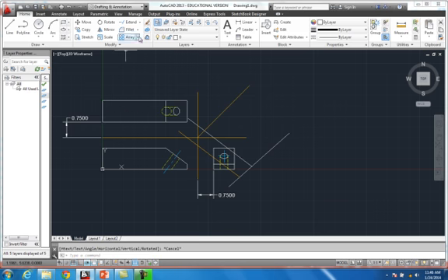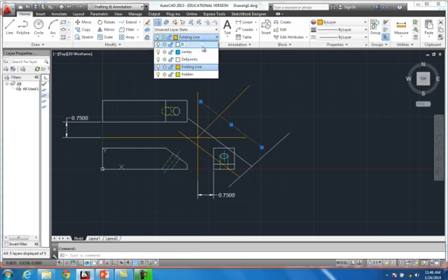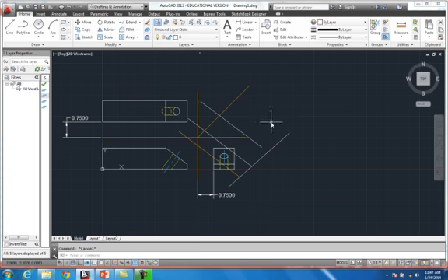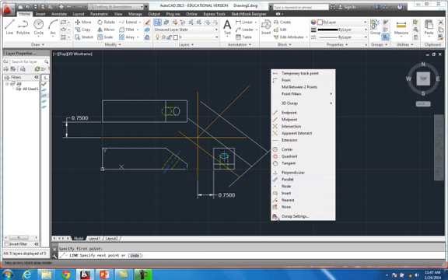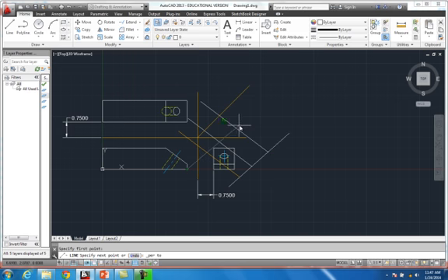So you can take at this point, hit the offset 1.75, enter, and go off this 1.75. Now that depth would be exactly right. Of course, I'm just going to put that in, and I want to extend it on out to that point, just like that. Now I've got that in there. Now I just hit my line, and I'm going to go from this point. It'll be perpendicular up here, control, and hit perpendicular. There's that point.